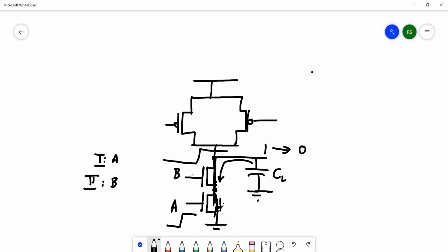I'm not changing that, but by giving the signals correctly, that is, the ones that come first, they should discharge the intermediate capacitances, and when the final signal arrives, only the output capacitance has to be discharged, which means that will happen very fast. In the previous case, first the signal came, but the capacitance was not discharged. So when the final signal came, both the output capacitance and the intermediate capacitance have to be discharged, which means it's going to take more time. So that is the idea behind this input ordering delay effect.